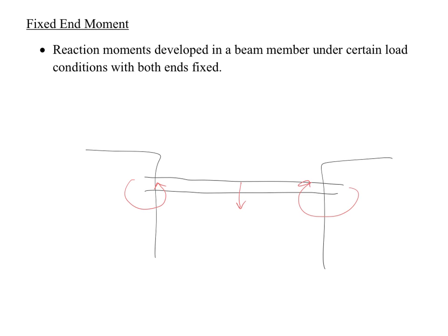So look at the moment. Which way is it drawn? The other way. It's a reaction. A reaction is always opposite of the actual value itself. So the same thing occurs for the reaction forces at the end. These are fixed end moments, but because the bridge has a force acting down, there's actually a reaction force also at the end pulling back up at both ends. We call these R. So this is like RY1, RY2, and this is M1 and M2.